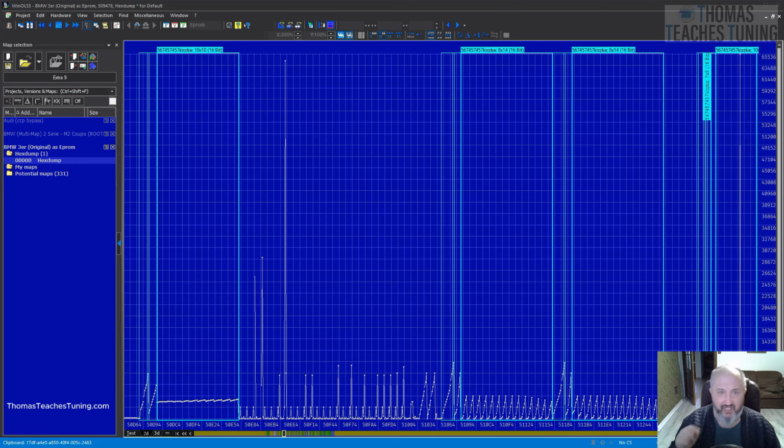The second major myth I have encountered is the belief that vehicles cannot be modified using percentage changes. Regardless of how we approach the modifications, whether by applying fixed torque settings, adjusting the conversion table from torque to fuel delivery, or making other operational changes, the outcome will still rely on percentage changes. It is because the fundamental operation of the engine is based on proportions. So proportions are percentages.